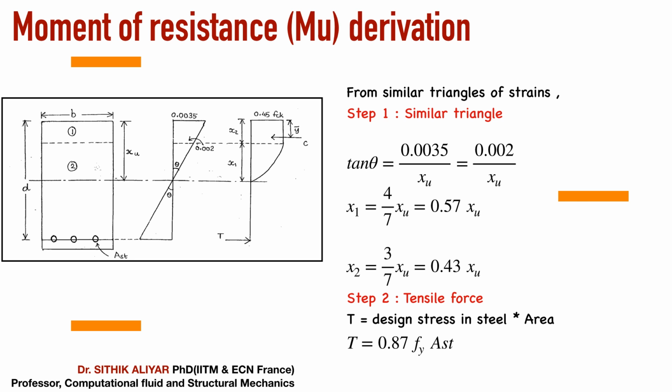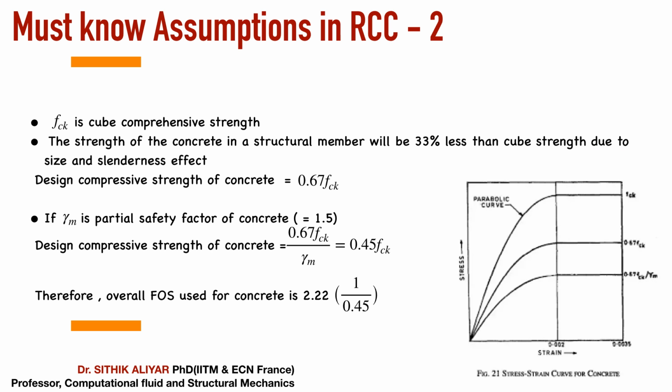Okay, so again, to make sure you understand, in this figure, up to 0.002 is section 1, I have assumed. From 0.002 to 0.0035 I have taken as section 2 because it is a straight line. So in the third graph, the third line you see, one section looks like a rectangle, one section looks like a parabola.